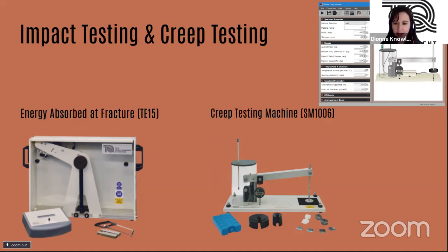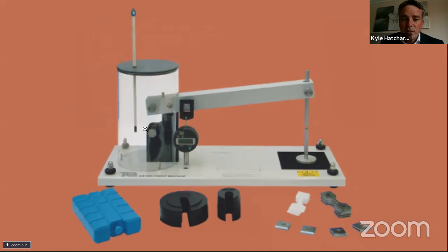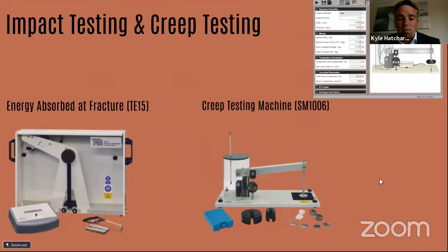Fantastic, Kyle. And we've got an ice pack there, shown on the picture. Can you explain more about how we use that with that piece of apparatus? Yeah, so the idea with the ice pack is that as you alter the atmospheric temperature, the material behavior changes. You place the ice pack in the freezer, and you can see that cylindrical compartment. Once it's frozen, you place the ice pack in there, and where you're hovering the mouse at the moment, Dion, you can see 2 notches, and you apply the specimen in the middle of that. The idea is to cool that chamber so that you change the properties of the material slightly, and you will see the reaction of the material change dependent on the environment it's in. So that's effectively demonstrating to students that creep changes and materials behave differently depending on the environment they're in from a temperature point of view.